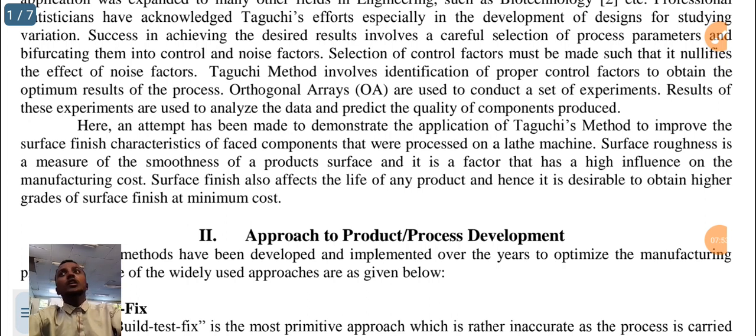For example, the specific components that are done in turning, that's called face turning, in facing operations. So these components of the product have to have a smooth outlook and a smooth nature after finishing machining, because mostly in the arrangement or assembling of components, for example like slots, right? Such a rough surface disturbs assembling in a basic machinery system.